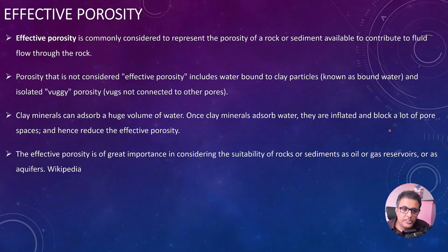Another important definition of porosity is the effective porosity, and the effective porosity is the porosity of those pores that contribute to the fluid flow. For example, the porosity that is not considered effective porosity includes water bound to clay particles.